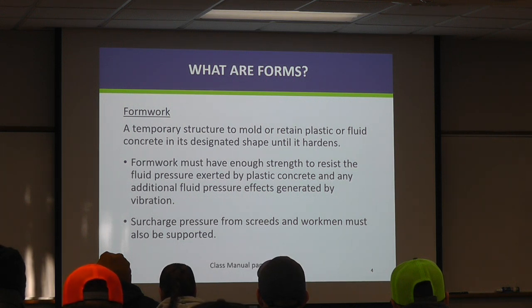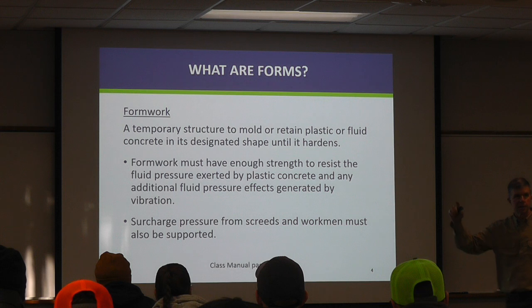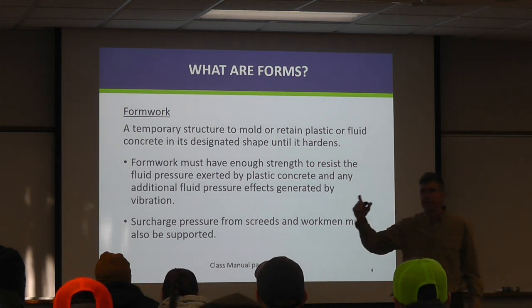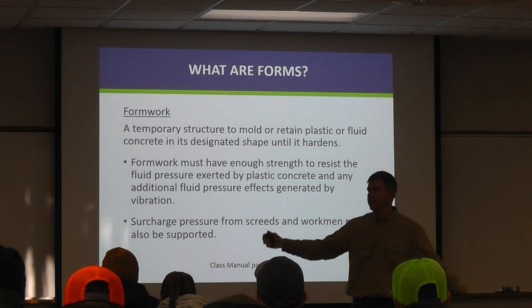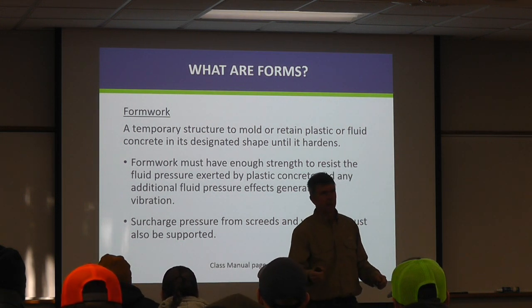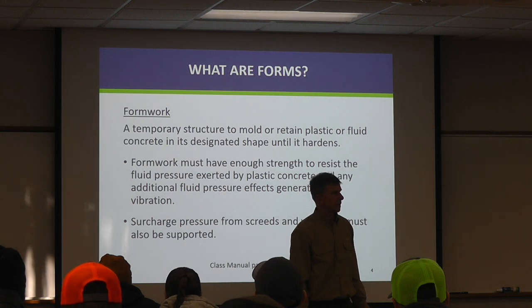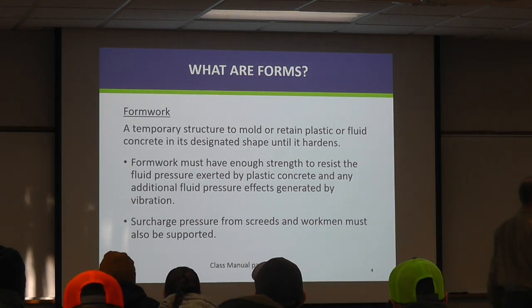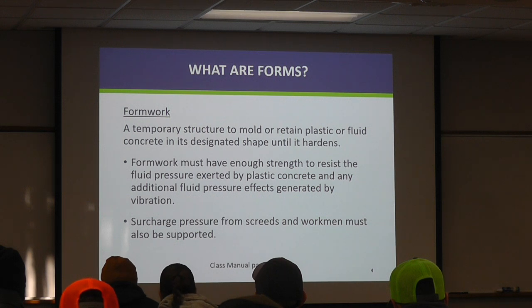Uncured or wet concrete has a lot of force that's trying to get out. Has anybody been around when you see a form failure of anything? You blow out and the concrete is all over the place. Yeah. So if you just have a little form and you tack a couple of nails in there, it's not going to last very well. And so there needs to be a thought process to withstand that.